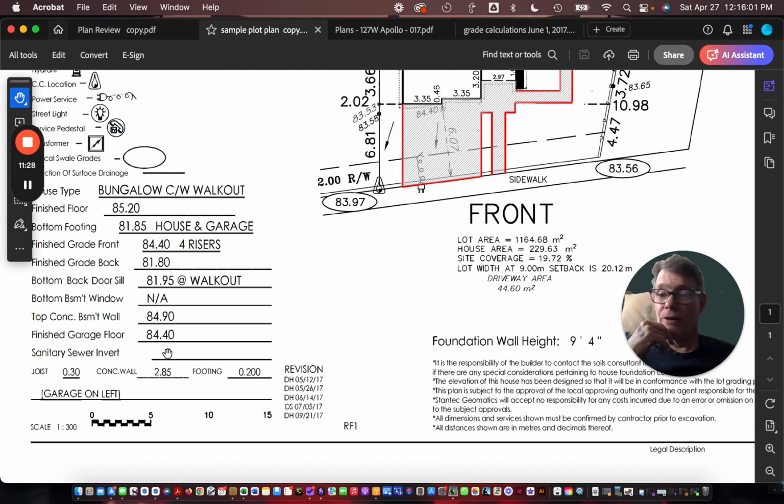Not always. Looks like in this case we don't have the data. This can happen sometimes, where a street is old and we don't have data on where the sewer really is. If we do have it, it'd be here on this line, and then we could do a calculation because we know how deep the house is, we would know how deep the sewer is, are we getting a good flow? Here we don't have this information. It's going to be more, honestly, it's a warning sign.